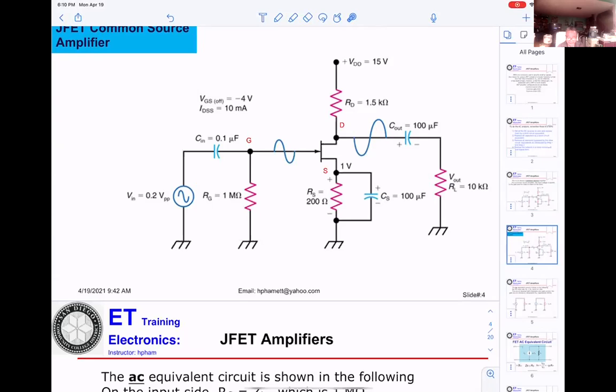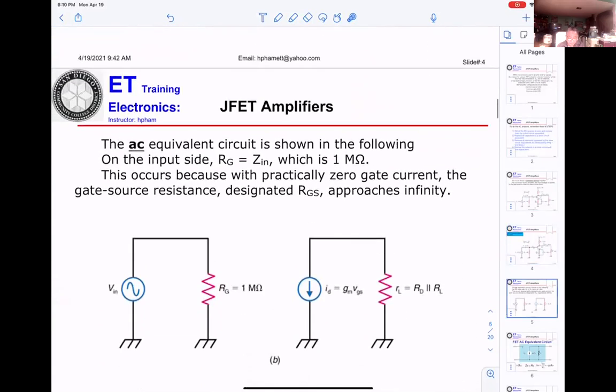However, when they go to the output, they don't want any DC, so that's why you get the C-out bypass. If you are an engineer designer, then you need to know what the value of the capacitor is supposed to be for good bias and good coupling. I think on the handout, maybe for the bipolar transistor, we already talked about that. Okay, thank you very much.